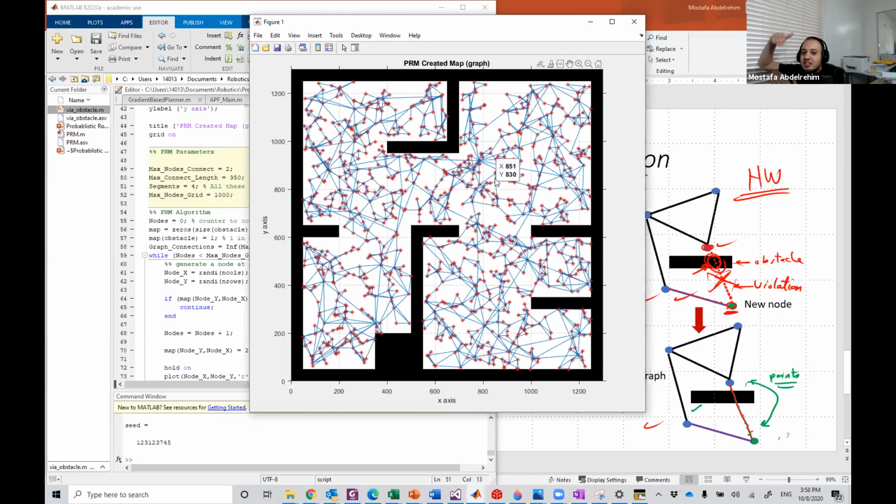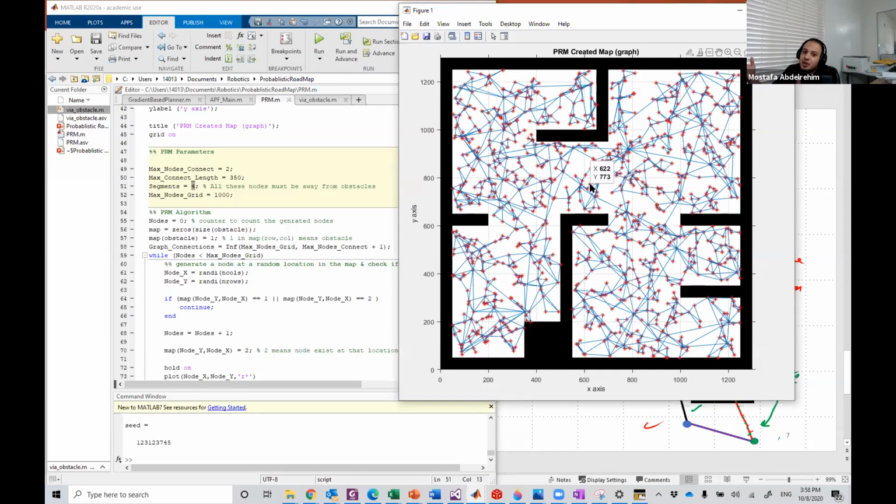Okay, so 10 was more than enough. That's what I'm saying. If you choose 10, you are too conservative. You will most probably end up with a map with no violations, but you make some extra redundant processing, which takes more time. But with 4, less than half of 10, you are still getting a valid map with no violations at all, and with less time as well.